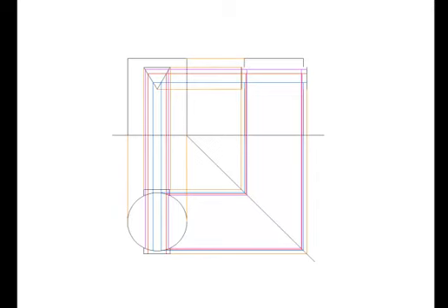Now, first of all, we need to locate where the base of the prism here intersects the cylinder. This is found by the blue line in plan, which is rotated up to the end view. As we know from the question, this is horizontally across till it meets the cylinder. So we can draw this in heavy till it meets the blue line, which creates the base of the prism.